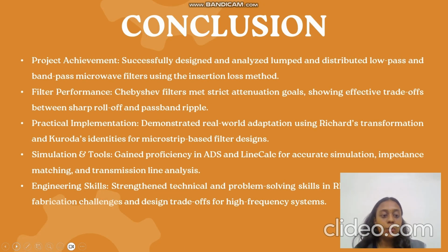From this project, we can conclude that it met its goal by designing and analyzing microwave filters using professional tools and proven techniques. We gained deep insight into RF filter theory and practical skills in layout and simulation. The Chebyshev filters were effective, and the distributed microstrip implementation taught us the challenges of real-world fabrication. Using ADS, we verified our design and handled issues like impedance limitations. This experience has greatly enhanced our knowledge and readiness for our future work in high-frequency electronics and telecommunications.